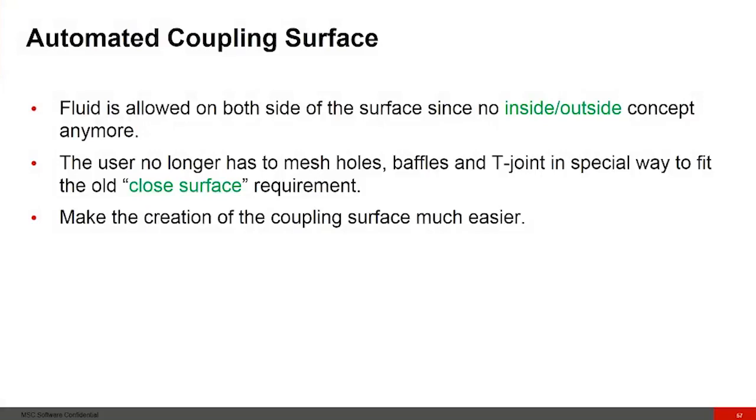The list of these shell segments is called the coupling surface, and it can consist of structure segments, but also some dummy segments. Before, to simulate these interactions, we used the fast coupling approach, which is often used, and it requires some intermediate and mesh techniques if you have the interaction.